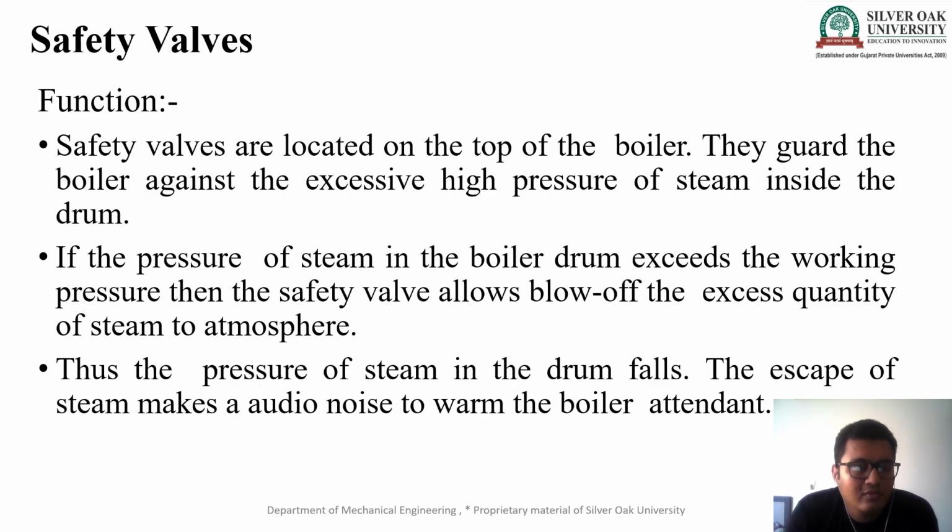Now we talk about the safety valve. The safety valve is also considered a mounting, and it is very important in the boiler. We have different types of safety valve, but here we cover the general function of the safety valve. Safety valves are located on the top of the boiler. They guard the boiler against excessive steam pressure in the boiler drum.